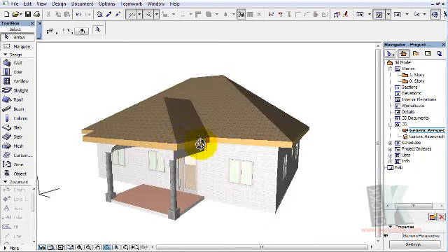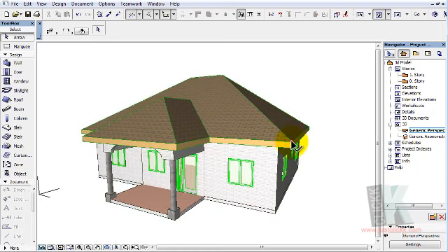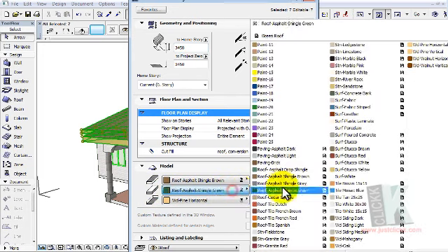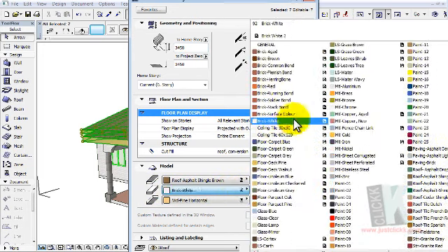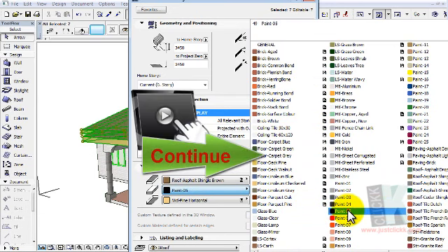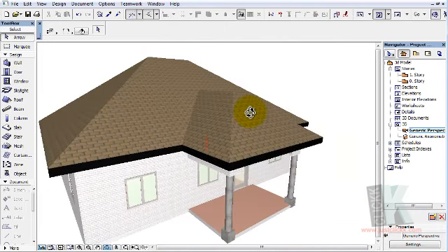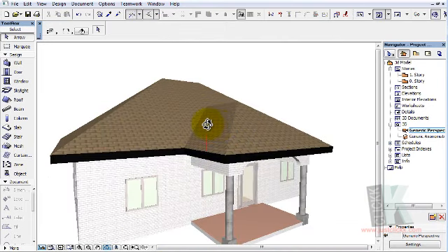Even the fascia board, you can select it, go back, and choose a color for it. This should be the fascia board. Look at the color codes here. This is the top, this is the sides, which is the fascia board, and this is the bottom of it. So let's click what color we want for our fascia board. Maybe we want something dark, so we'll pick this black color. That's it. This roof is based on the hip roof style.